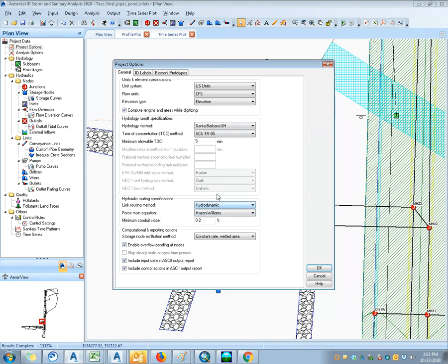What exactly is hydrodynamic? I know what kinematic wave theory is. I think it's that advanced hydraulic modeling where it's doing a volume balance and a momentum balance, so it can go forward or back. What is it called? The St. Venant equations. I'm assuming it would explain it in the SWMM manual. Yeah, you can look up their manual.